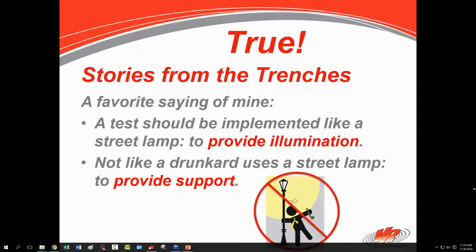Another way, when you hear it, the question might be, where is that coming from? And of course, the engineering way as well, let's put accelerometers all over it and find out where it's coming from, and that is a good way to do it. But another quick way to do it is use your fingertips. They're actually very good sensors. And I implore you to wear earplugs because I've done this for years, not probably with the hearing protection I should have, and sometimes these resonances get very, very loud.